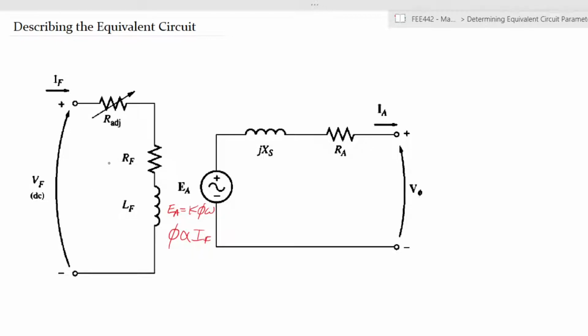As we had said last time, the three-phase synchronous generator consists of the field windings, or the field part of the motor, mounted on the rotor, and the armature, which is on this side. So we have stator and rotor. The rotor is supplied with a DC field current, which determines how much flux will be available within the stator. As the rotor windings are rotated within the space of the motor, an induced EMF will be induced on the stator side in all three windings.